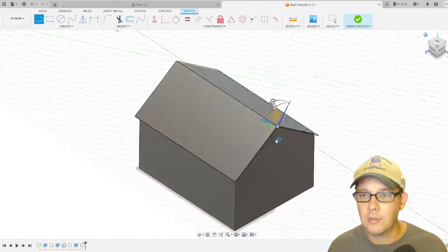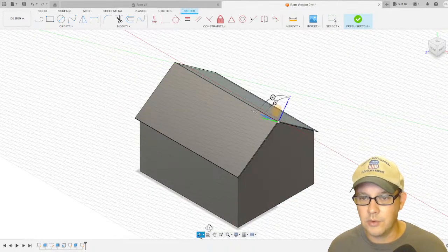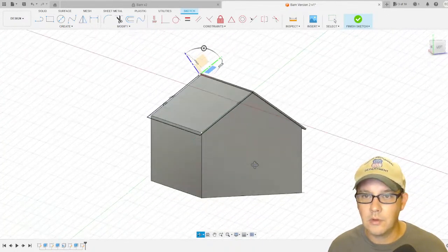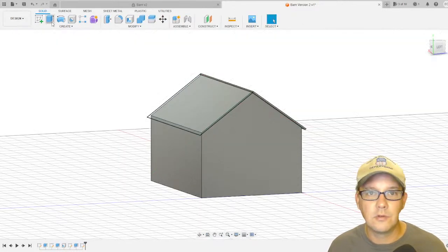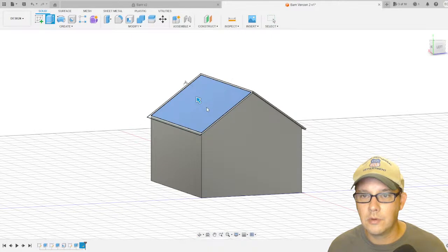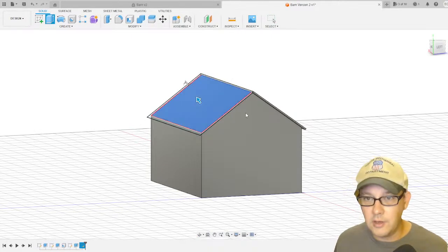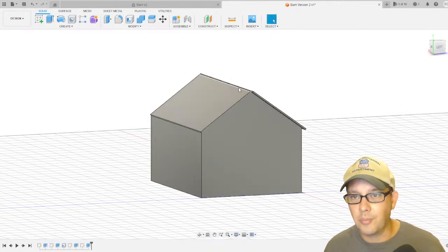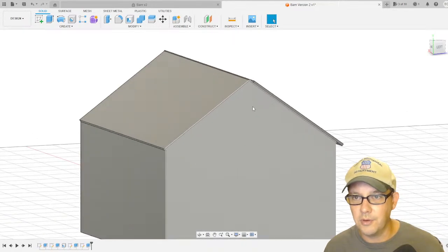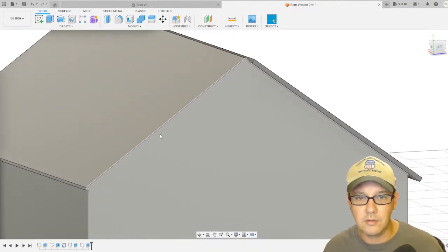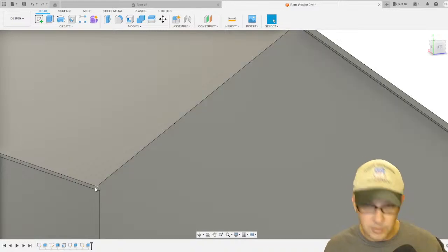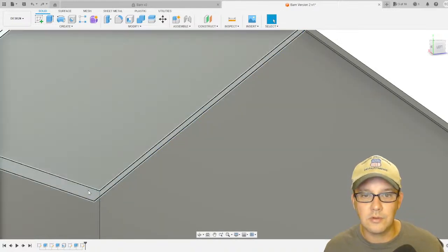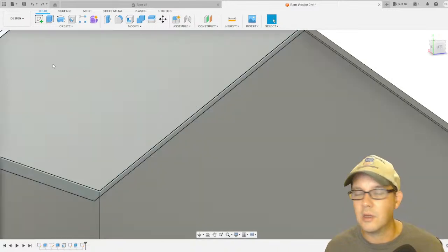Go back into my top mode. And then we're going to go here, solid, finish sketch, extrude. 0.8 is my thickness. There we go. And now I probably have some weird stuff going on up here, so I want to take a look at that. Oh, you know what? Look at that. Something didn't work the way I wanted because it looks kind of wonky. So we're going to stop. And it looks like I have that same thing I had before.